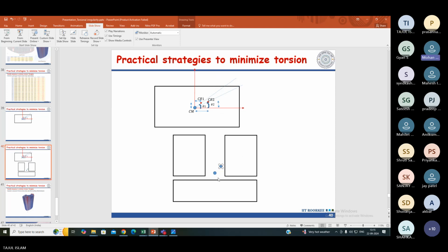So generally you will get torsion, right? Yes. So this is what is happening here. Now in this case, whatever procedure we have explained, you can try to satisfy it, because if you make this structure and this structure rigid, it will have torsional resistance. So you have to provide the vertical resisting members appropriately in this and this structure, but not much in this structure, as I understand.